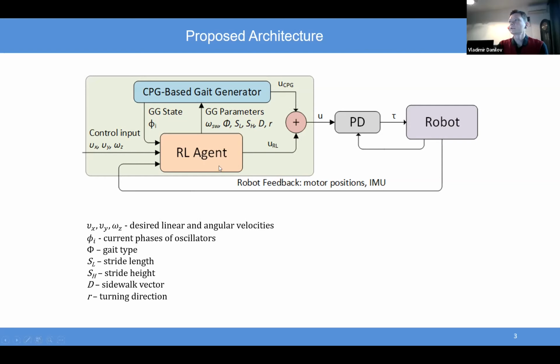Here the goal of the trained agent is to set the input signals for gait generators and to optimize its output signals, output values of joint angles in this situation. My contribution here was that I decided to use the gait generator based on CPG network because it allows to change stride frequency and different gait patterns online and smoothly.